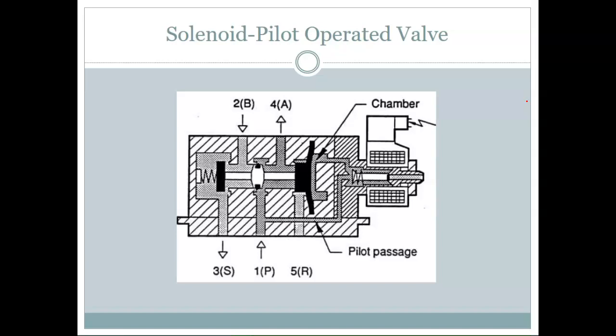It's a 5/2 or a 5/3. Can't really tell based on the drawing here because the way it's going to actuate is it's going to end up pushed against this spring. In its normal position, when you push back this way, the A goes there. That's your pressure line. So I believe this is a two-way. I'm sorry, a two-position 5-way.